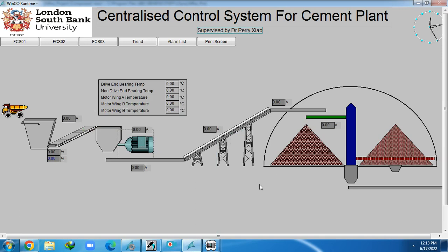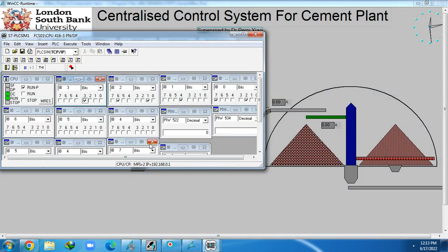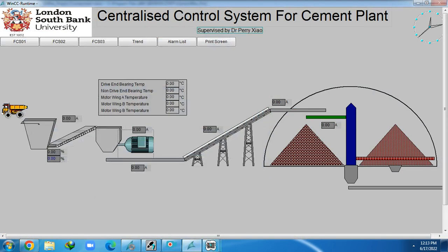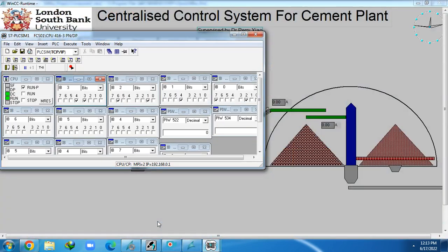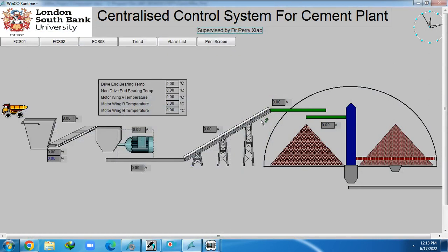The first motor is started. Now I need to give the state signal. This is the signal that this PLC is expects from the electrical cabinet. Once I give that, it will wait for another 5 seconds and it will start this belt. That's done. Now I need to give this state signal, which is actually conveyor belt 3. Conveyor belt 3 state is 2.7. Once I've done that, it will wait 5 seconds and start another motor.